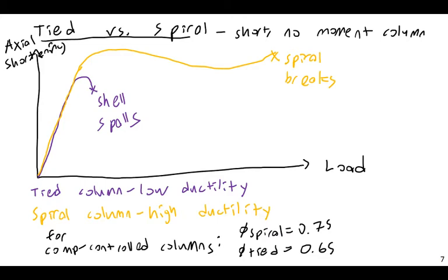Again, we know that brittle failures are much more devastating than ductile failures. Why would we prefer a ductile failure to a brittle failure? Exactly, because it's absorbing energy as it fails. It's deforming quite a bit before it fails. And what that really gives you is notice. If you notice that the beam is deforming a lot, cracking and bending really strongly, that gives you time to make sure you're not standing underneath it when it finally fails.